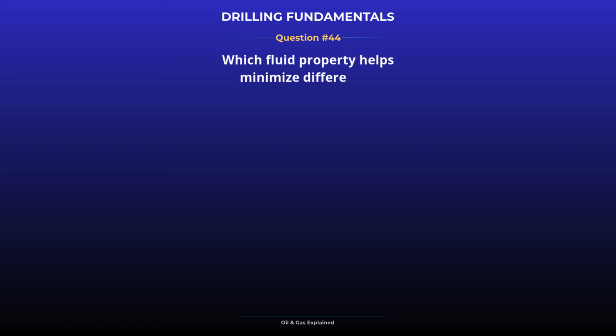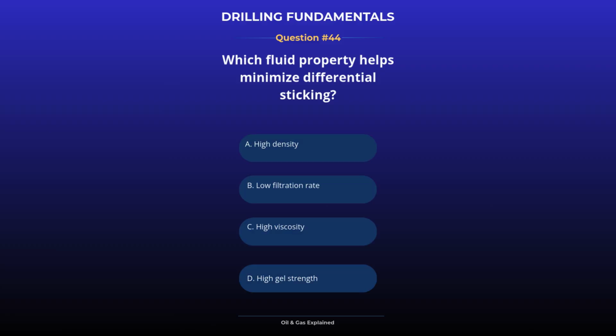Which fluid property helps minimize differential sticking? Low fluid loss reduces filter cake thickness, minimizing differential sticking risk.